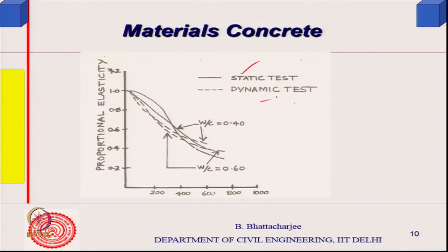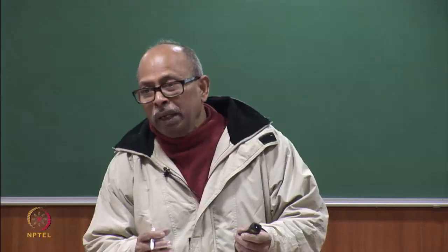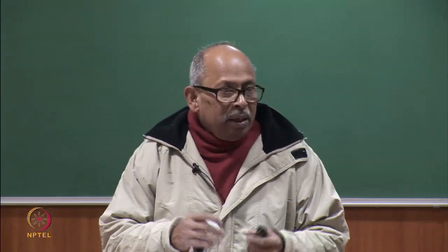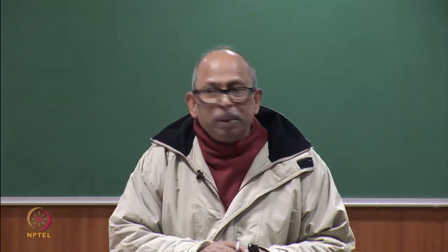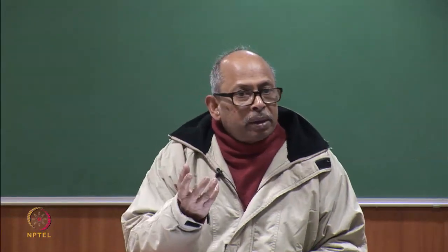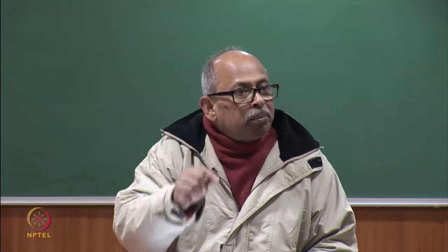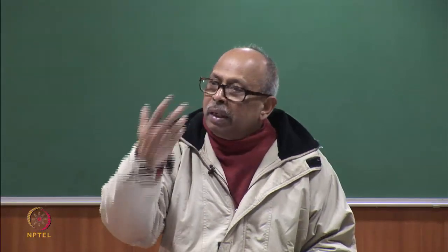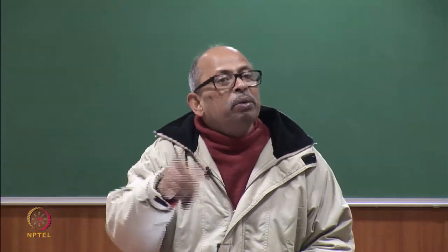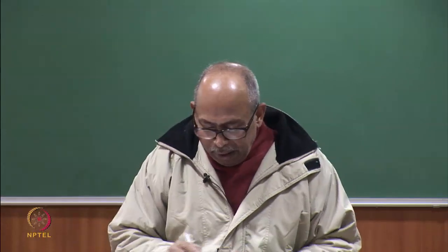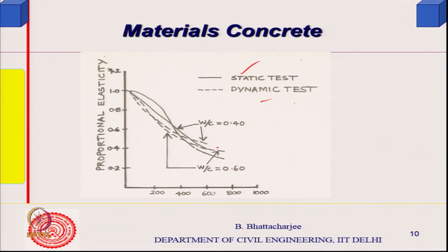Static test and dynamic test. What is a dynamic test? In a dynamic test, actually you preload it, increase the temperature and do it again, right. So, static test is basically you increase the temperature, then do a static test only. In the dynamic test, basically you put some load, increase the temperature to the required temperature, then again do the stress strain behavior. Both these types of tests have been done, but in either case you find the relative elastic modulus tends to come down, whether the water cement ratio is 0.4 or 0.6, it will come down.